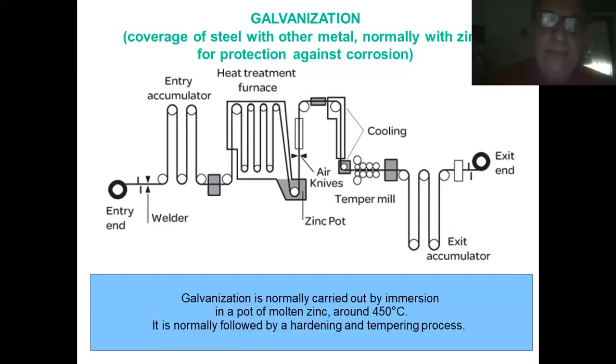Stable mostly because they are chemically stable, in the sense that they don't allow corrosion to penetrate, and they are also quite thick. When I say quite thick, I mean 100, 200 microns, which might be sufficient to provide the defense against corrosion.